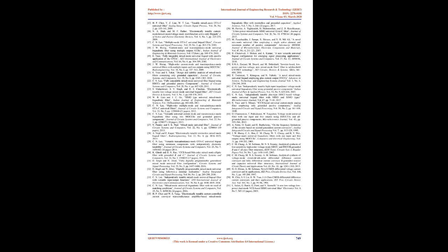The proposed circuit can be operated in general mixed mode, i.e. VM, CM, TAM, and TIM, and can realize all 5 universal filtering responses, low-pass, high-pass, bandpass, notch, and all-pass, in the general mixed-mode applications without changing the filter topology. Moreover, the proposed circuit has no need of component matching constraints for VM and TAM all 5 universal filtering responses.